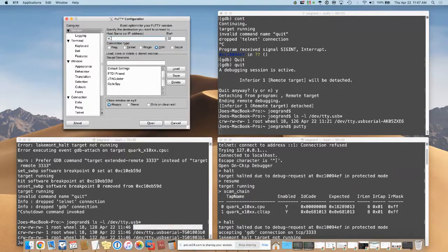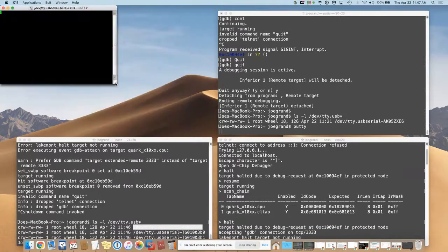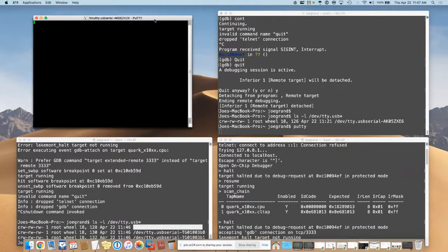Yep. All right. So I'm going to blast through these because they're fun, and then we'll try to answer as much as I can. So I had to reload PuTTY because that cool term broke. So I'm at 115,200. Okay, so I'm going to connect to the front door of this Galileo device. And let's see, I'm going to power cycle the board. We should see some data on here if I got it right.